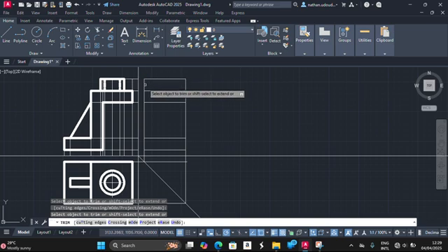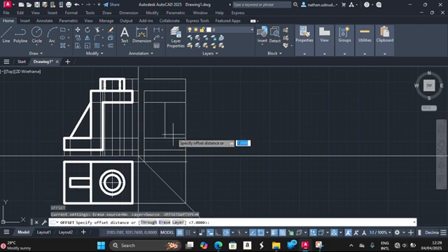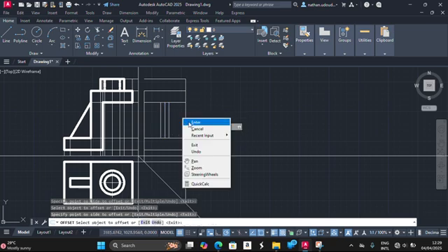So you can also trim up this like that. So right click and then left click. So L enter again, and then you can take up the midpoint here, from here to this point, left click. So now the wedge, of course, is already having a thickness of 14. So you can take your offset, O, enter, 7, enter, 7 is already there. So offset it to the left, offset it to the right. So that's one way you can do it.